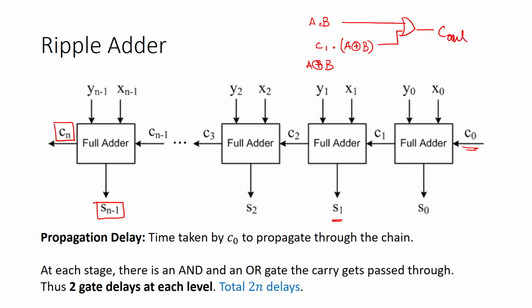So this is the out and this is the in. At each stage there is one level of AND operation and one level of OR operation. So there are two logic levels. First level we have to do some AND operations, next level we have to do OR operations. So if each logic gate is supposed to have some delay, we can say that there are two gate delays.